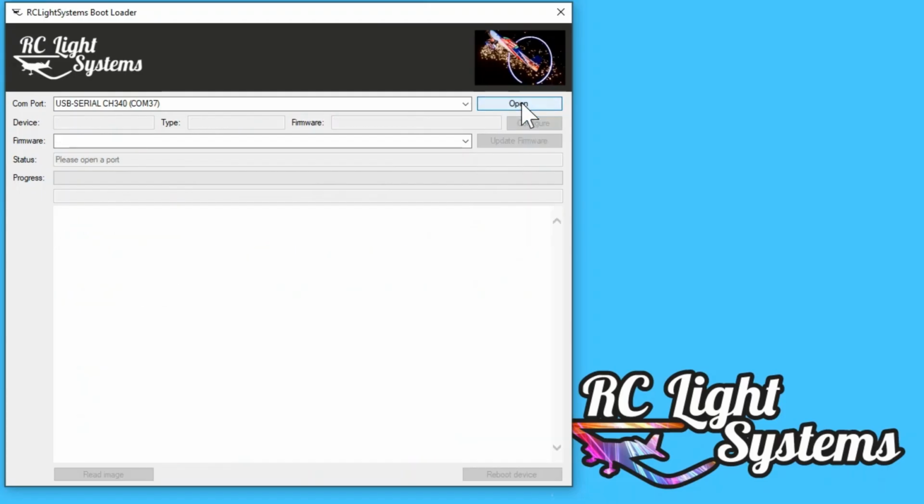Now, where it gets different is where you use the bootloader with a standard dongle. Our dongle has power switching in it, so it makes it much easier. You connect it all up, then you click open, it then activates the power and then talks to the device. With a normal dongle, so if we pick the Powerbox dongle that I've got connected here, I haven't yet connected the wire on the dongle to the serial expander. I click open first, it now tells us to connect device, and I now plug in that connector to the device,